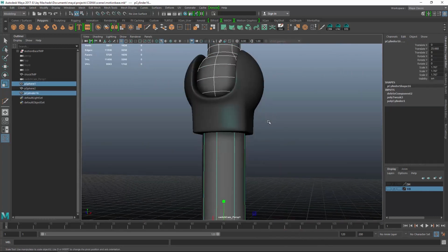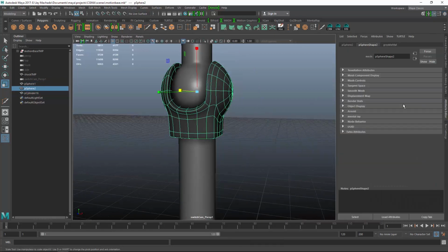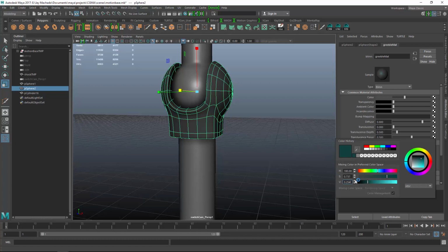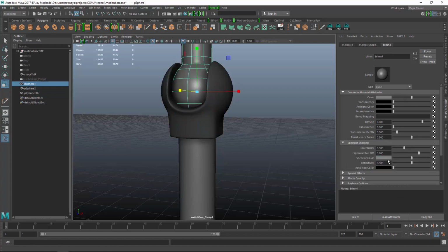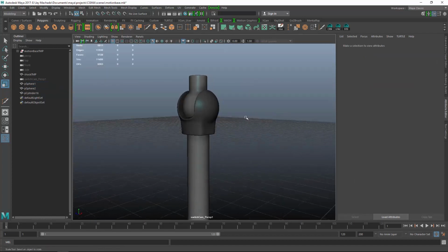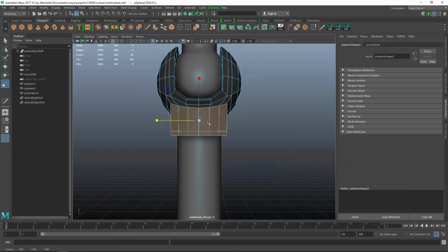And I'm actually going to create a second Lambert material, and it's going to be very similar to the first one, but I want it to have the same spec color values. So what you can do in that color picker window is if you change one of the parameters of the colors, it saves it in that little shelf, so you can come back to it.